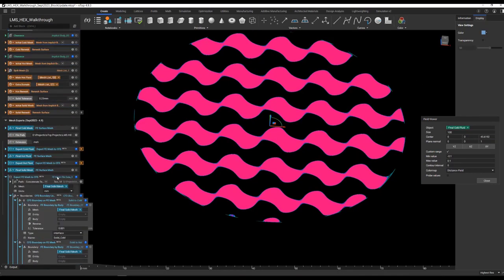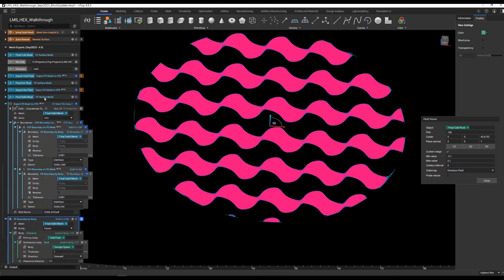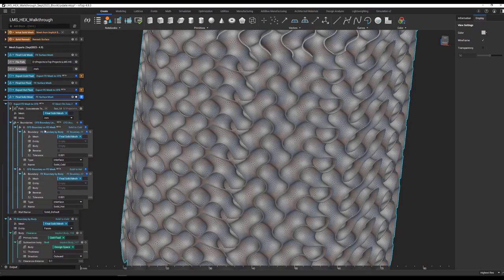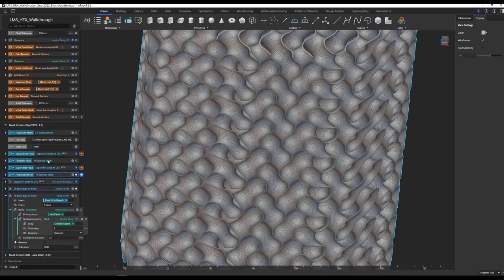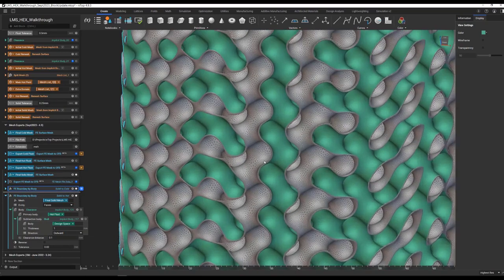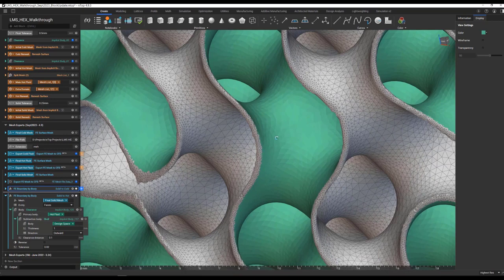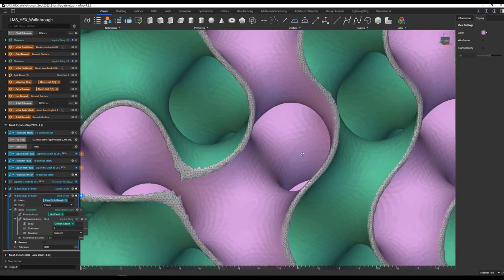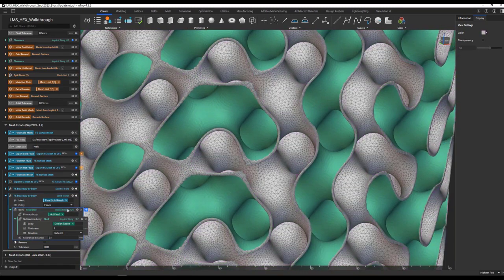So what we'll ultimately use to select our boundary condition faces is this cold fluid domain. So we'll get to that here. I'm going to isolate just the solid mesh, minimize that, and turn this guy on. So the green now is the interface between the solid object and the cold, and the purple is the interface between the solid and the hot. You'll notice, however, I have one extra block in here, and that's the clearance block.